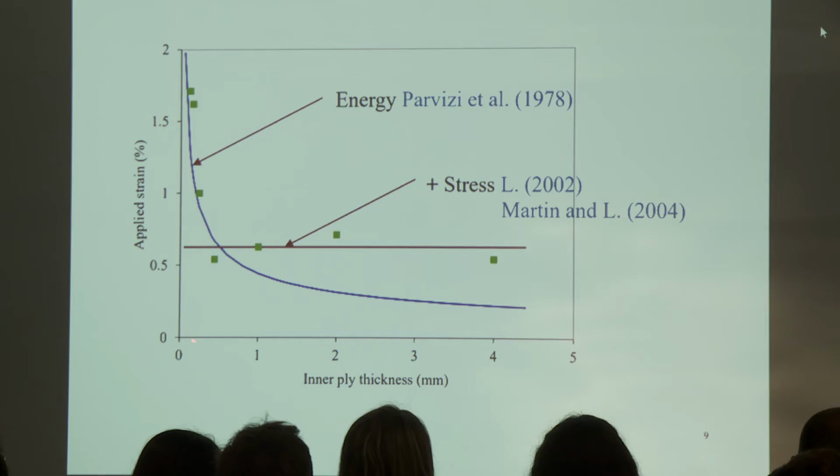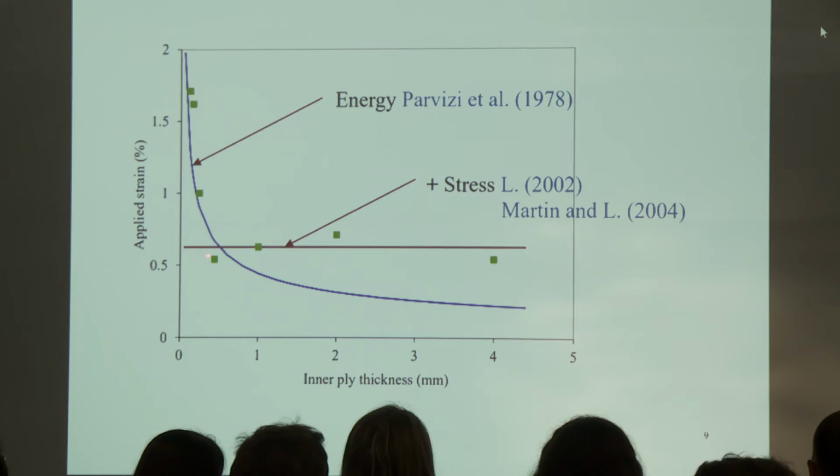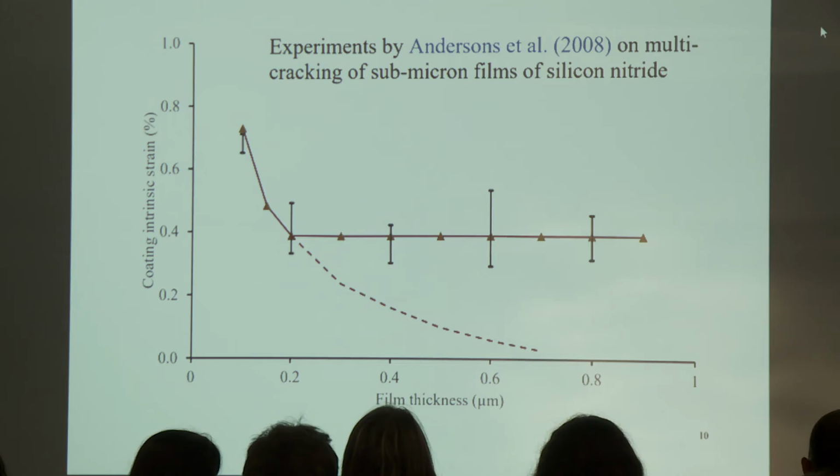On the contrary, if it is a very thin layer, you reach the stress condition here, but you still have to increase the load in order to have enough available energy to create the crack. This is the idea for starting the coupled criterion, and this kind of curve with a plateau and then an increase is met in many cases.